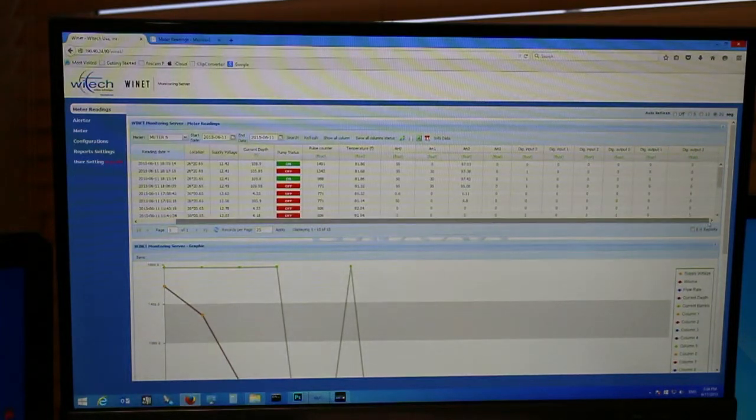You can't go any farther from here just because I haven't set up the unit with Modbus registers. If the unit is reading Modbus registers, then let's say you program 1 or 5 Modbus registers, they are going to show here to the right. Okay, and you can rename those to whatever it is on the meter. Let's say total volume or flow rate or units or anything that you want. You will be able to have them here to the right, up to 15 Modbus registers. Okay.